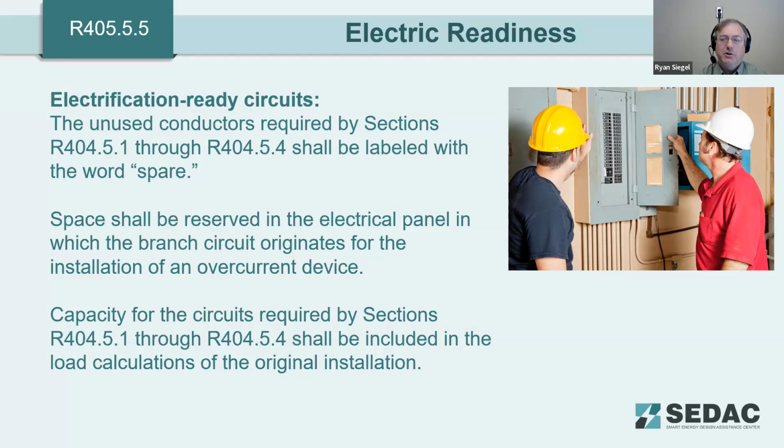So obviously we're going to make sure we leave room not only for the wires that we've run to the space, but we need to make sure that we've left space in the panel to install the breaker if it's not installed at the time of installation.